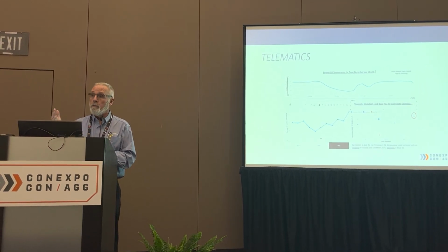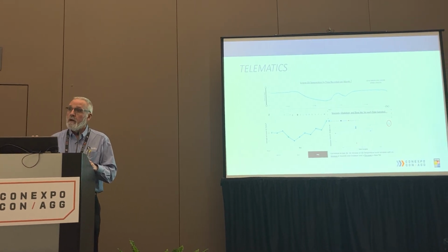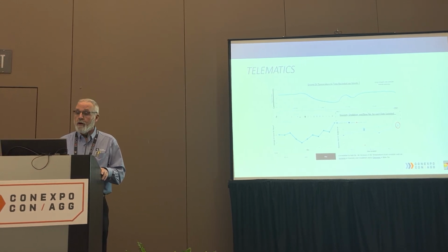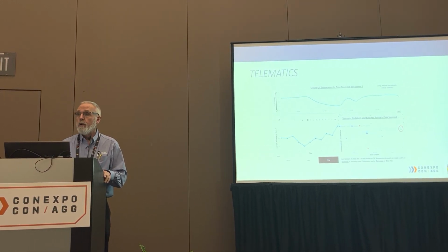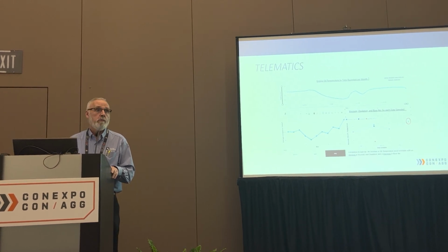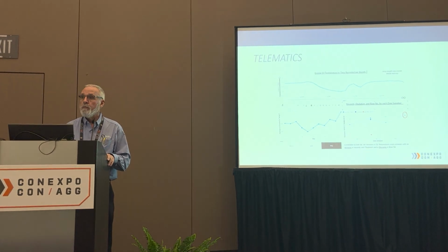So I went with their telematics data, and I started looking at operating temperature, and there was a direct correlation, as you can probably appreciate, to say, all right, you can safely extend your drain interval to 500 hours as long as your engine operating temperature is below 230 degrees.